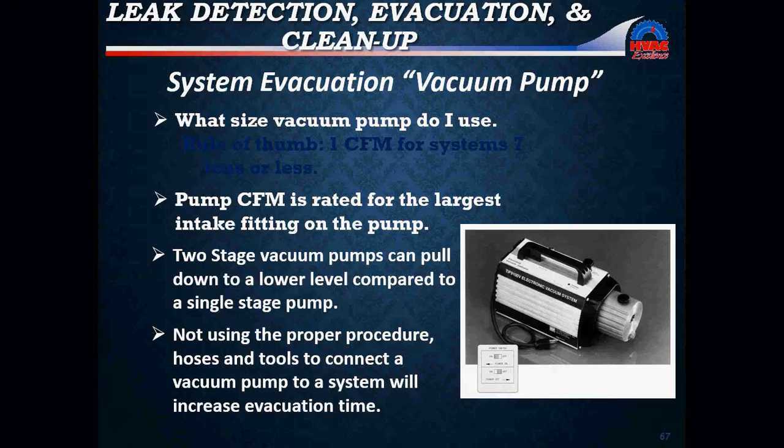Your pump's CFM is rated for the largest intake fitting on the pump. 2-stage vacuum pumps can pull down to a lower level compared to a single-stage pump, and not using the proper procedures, hoses, and tools to connect the vacuum pump to a system will increase evacuation time.